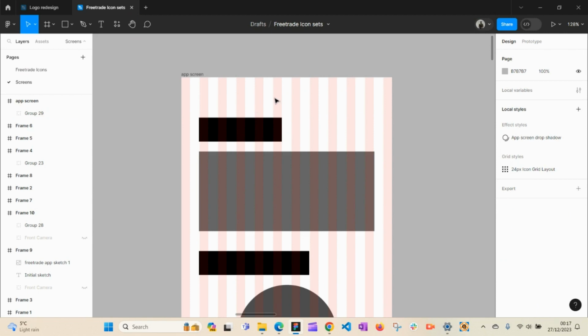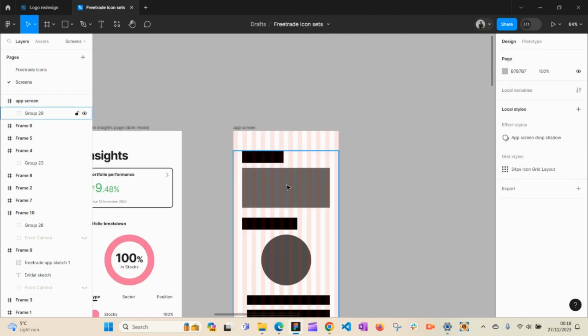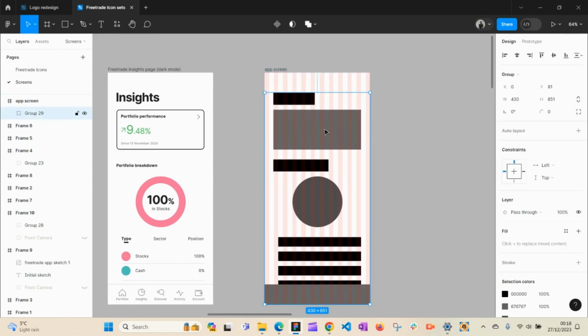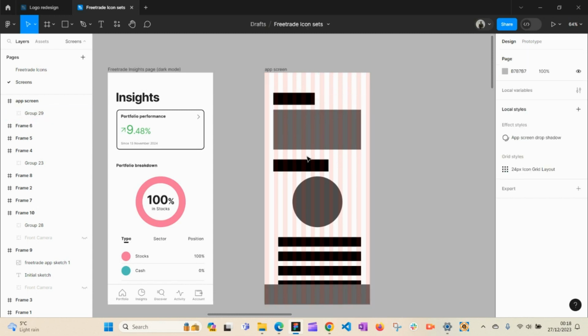But make sure, what I did was, let me draw the initial rectangles here. You will see, if I zoom out and press down on the Alt key, it's going to show you the length between elements. It's actually quite measured. The space between the top and the first element is 80 pixels, and the spaces in here are 20 pixels.